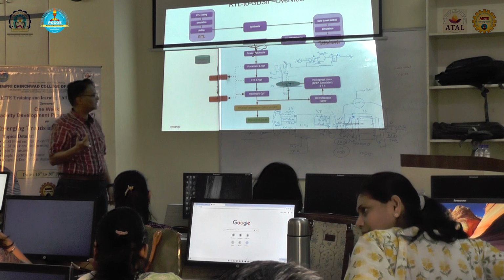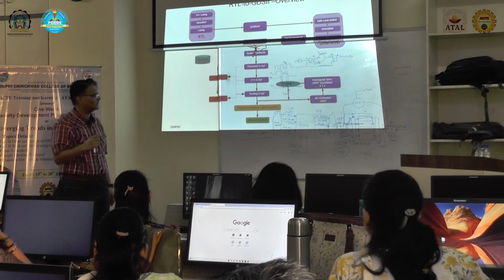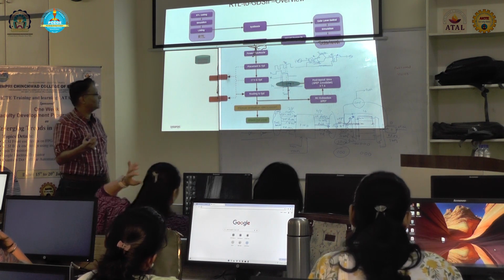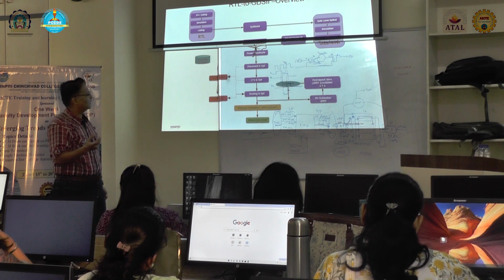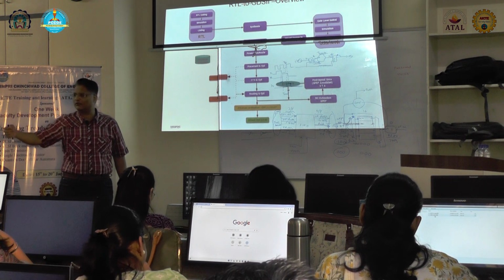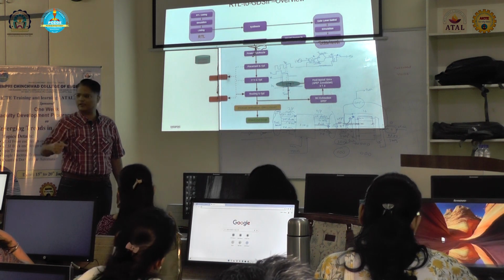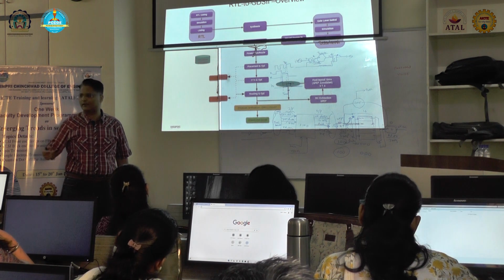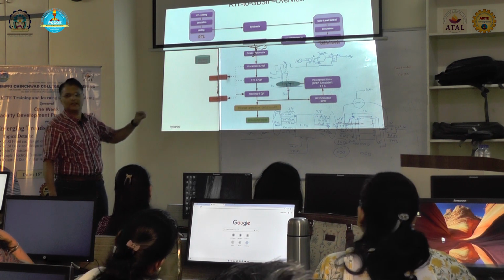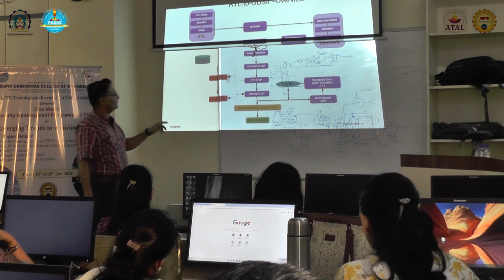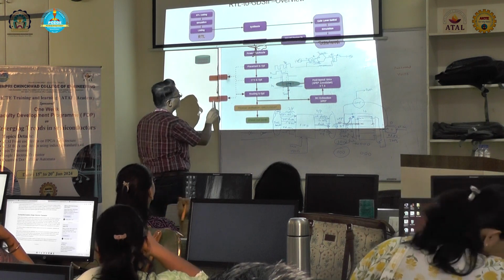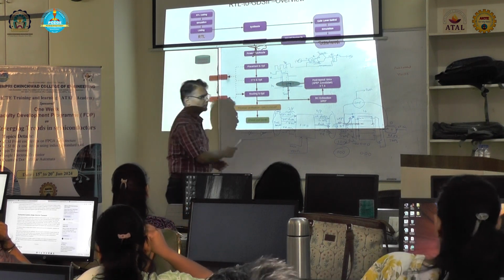And antenna checks are something where you might pick up some noise. Okay? If you have very long wires running in the chip, then they are very susceptible to interference. So for those kinds of things, we have to do some antenna checks. Okay. Now, if you see here, there is a power integrity and a crosstalk check being performed.